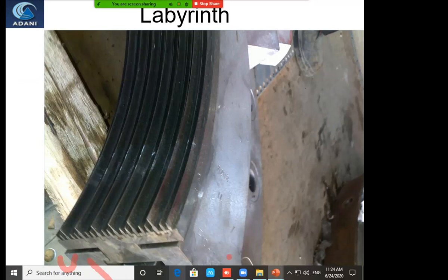How is sealing done? There are a number of labyrinths. They minimize the passage, and the pressure will drop. The high pressure steam will be dropped again and again, and it will lose its pressure ultimately and stop leaking from the outside. Next.